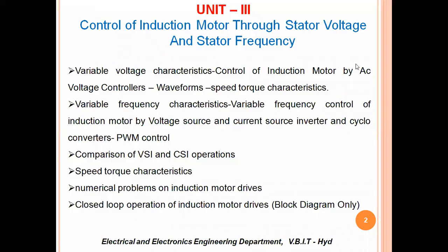Here you can see clearly the variable frequency control of the induction motor can be carried out with the help of voltage source inverter and current source inverter. So VSI and CSI, along with the cycloconverters. We know what is voltage source inverter and what is current source inverter. We have seen it in the power electronics subject. With the help of these inverters, we can vary the frequency and control the induction motor.